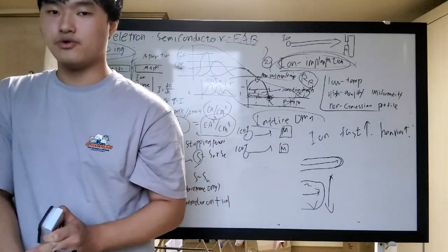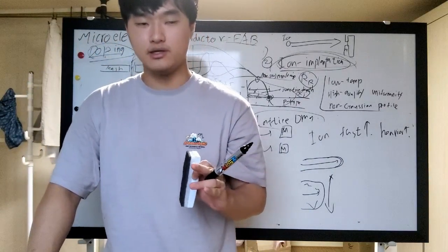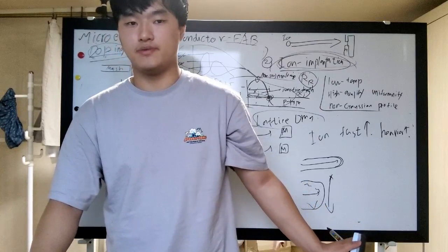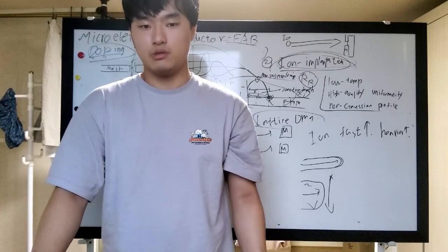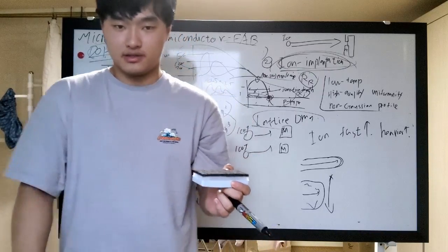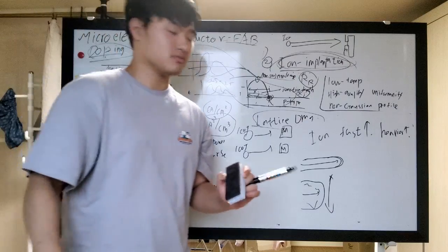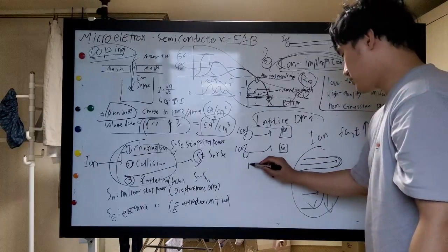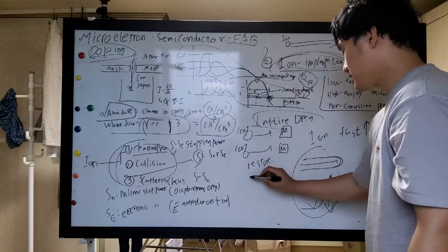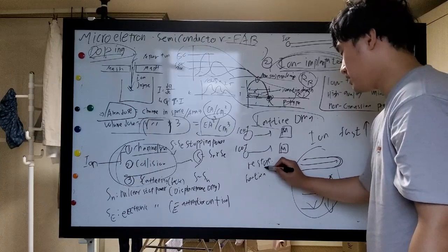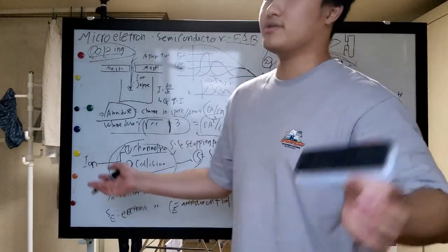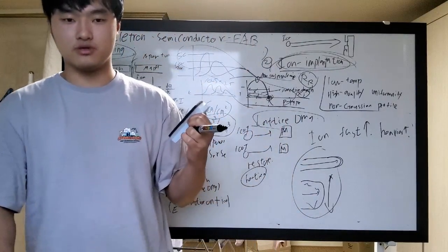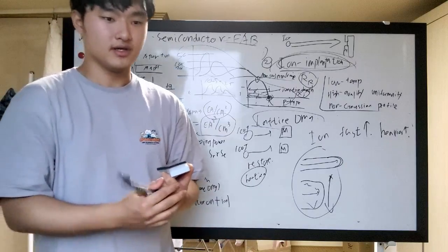When processing silicon that was polycrystalline or crystalline, within this process the silicon is changed to amorphous. At that moment, restoring is available in the heating process. When heating, the bonds will be linked again, and then the amorphous silicon will be changed back to polycrystalline or crystalline. So restoring is finally available within the heating process.